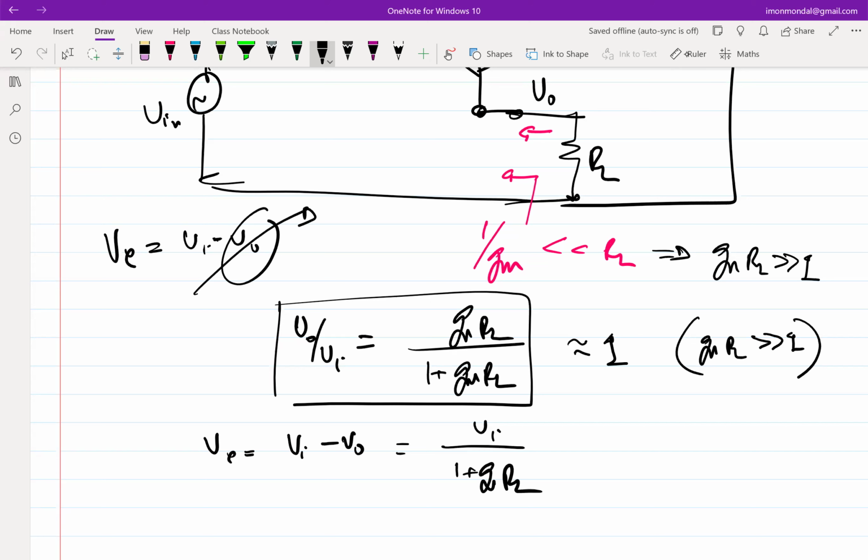Right? I want a voltage source to be independent with respect to load. Because if it's a ratio, I can use a common source amplifier and still set the gm in such a way that gm is equal to 1 over RL, so that gm times RL becomes 1. But then RL can go in different directions and the gain changes. So a voltage source should be able to retain its properties even when the load changes. That's why we need to impose this condition. But very good question. Does that answer? Okay, fine.